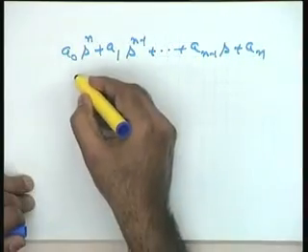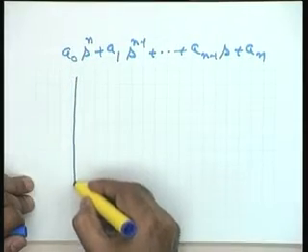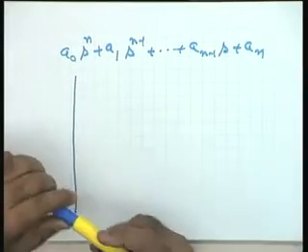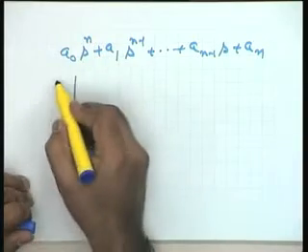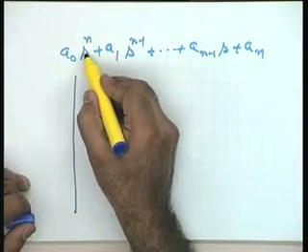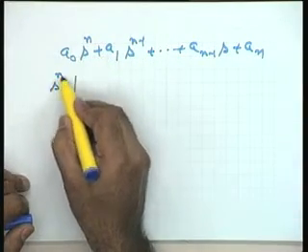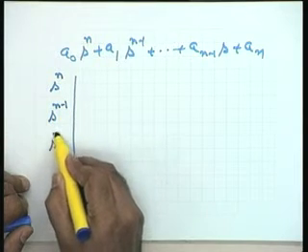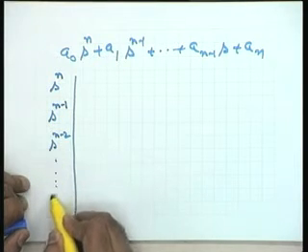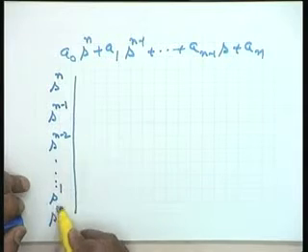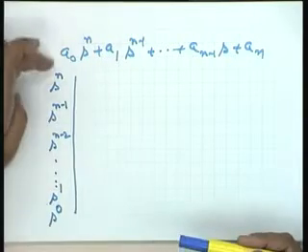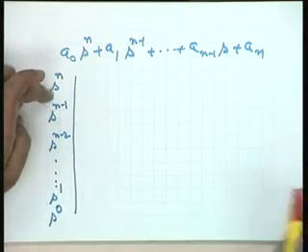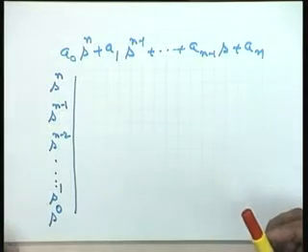I form a Routh array, an array formulation, and from the array formulation I will be able to make a conclusion regarding the criterion. So, the first term is s to the power of n. Let me write here s to the power of n, s to the power of n minus 1, s to the power of n minus 2, and s to the power of 1, s to the power of 0. This is simply a count of the rows, you see. So many rows are involved, and I am keeping this as an index of the number of rows.